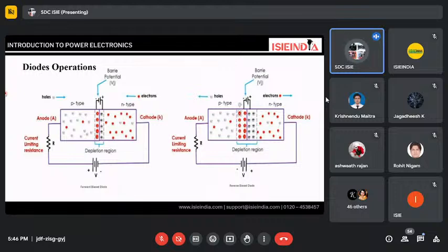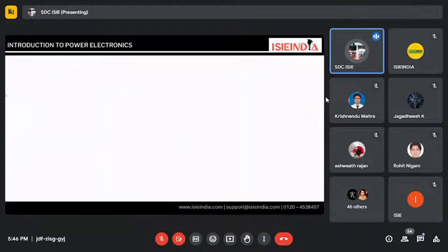So we basically connect one diode in parallel in each of the cells, and we have seen that even if one of the panels or cells is not working, it doesn't affect any of the other cells which are connected in parallel or series. Whatever desired output we are getting, and if somehow we have an imbalance, it can be rectified. So diodes are used for bypass connections in electronic circuits also.